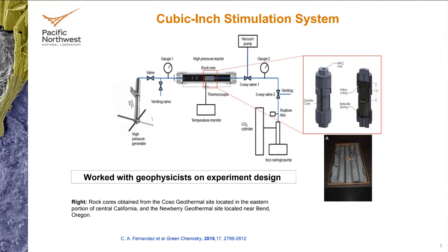And then we injected water or polymer solution, followed by injecting CO2 to generate the fracture. So first we add about 200 microliters of polymer or water as a control experiment, and then we add CO2 at a constant flow rate, until we see that this pressure gauge and this pressure gauge equilibrate, meaning the fluid has broken and the sample has fractured and the fluid has communicated from inside the wellbore to the confining fluid.